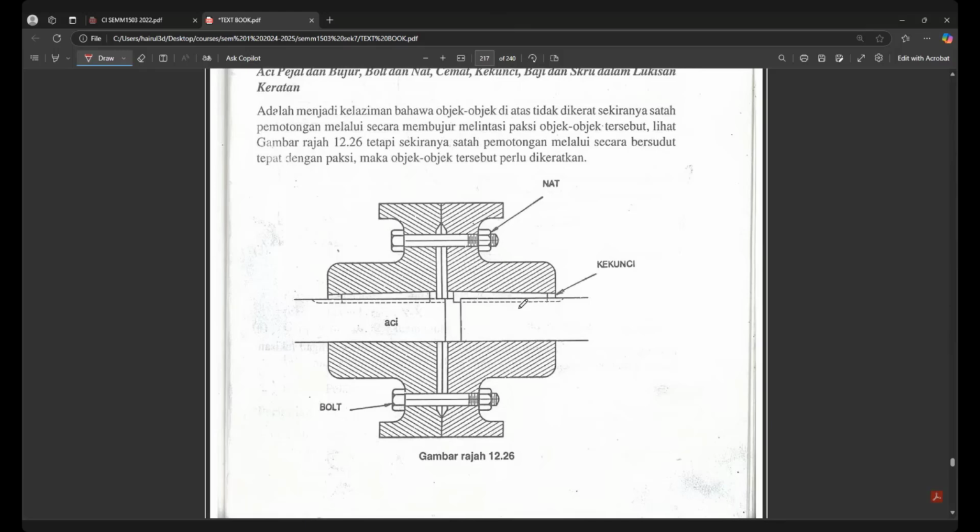When you're cutting some inside holder for battery, you have certain components to be shown in your assembly drawing, and you introduce full sectioning.